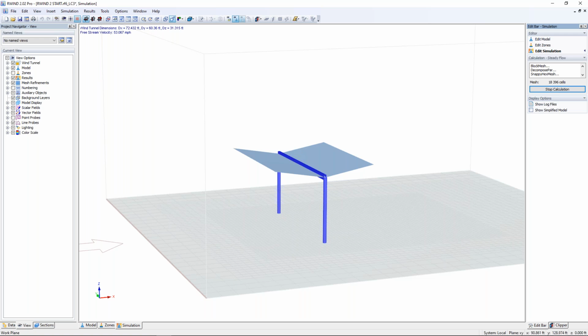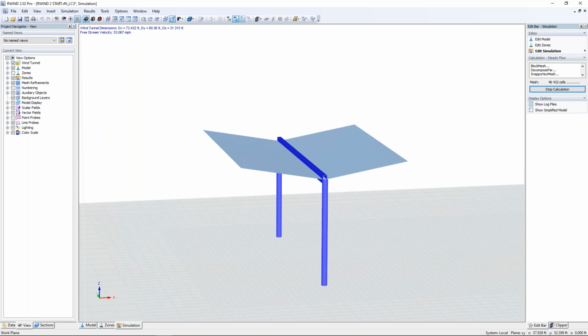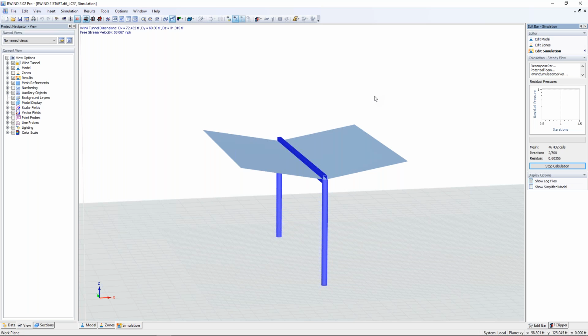Again, we can activate this option to hide all of the objects within RFEM. So you see here only the surfaces are drawn. So what we should see with the wind analysis then is these applied wind pressures only at the surfaces. When we bring the pressures back into RFEM, we convert them to loads. Those loads will only be applied to the surfaces as well as the three members you saw here. And then based on that load transfer, the program will go ahead and distribute to the members.